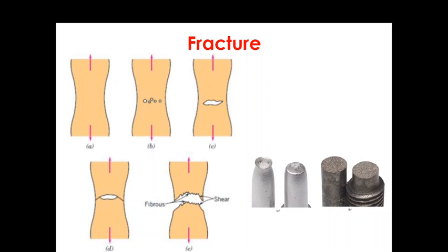And this crack has its long axis perpendicular to the stress direction. So the crack continues to grow in a direction parallel to its major axis by this microvoid process, which is shown in this particular figure. You can see the crack is continuously growing. So finally, fracture occurs by rapid propagation of the crack around the outer perimeter of the neck, by shear deformation at an angle of about 45 degrees with the tensile axis. This is the angle at which shear stress is maximum.